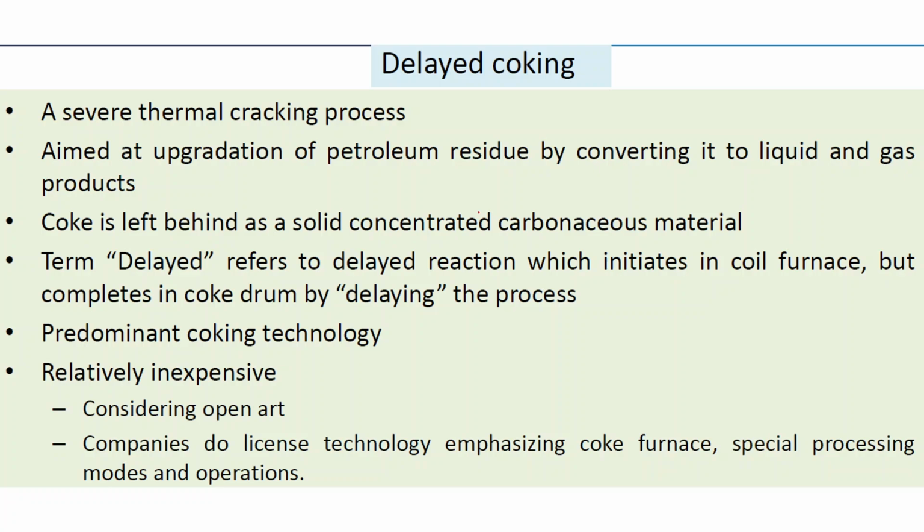So in delayed coking we do the coking, but the residence time here is more. The term delayed refers to the delayed reaction which initiates in the coil furnace but completes in the coke drum by delaying the procedure. So basically the time taken for coking here is more. It is a severe thermal cracking procedure aimed at upgrading petroleum residue by converting it to liquid and gas products, predominantly relatively inexpensive.